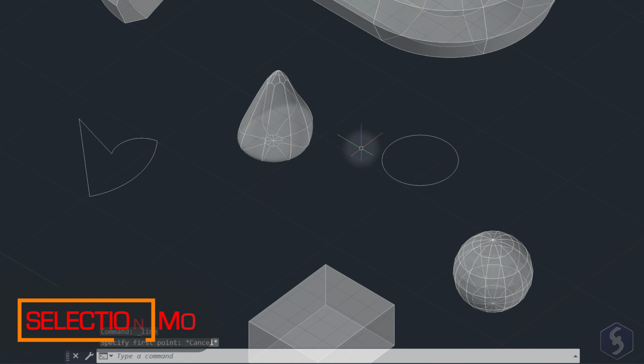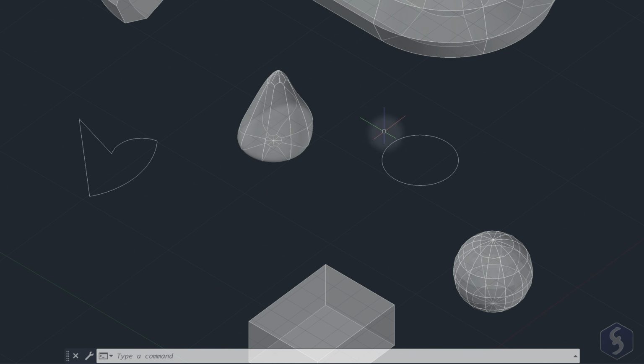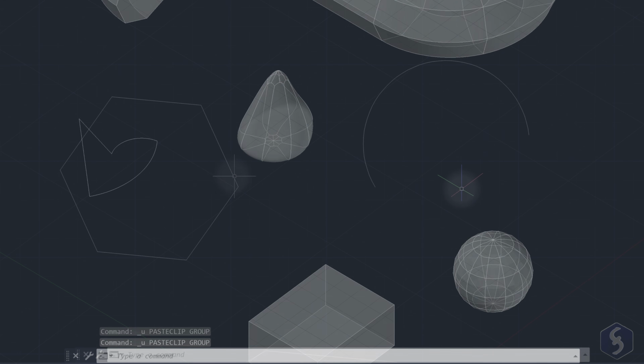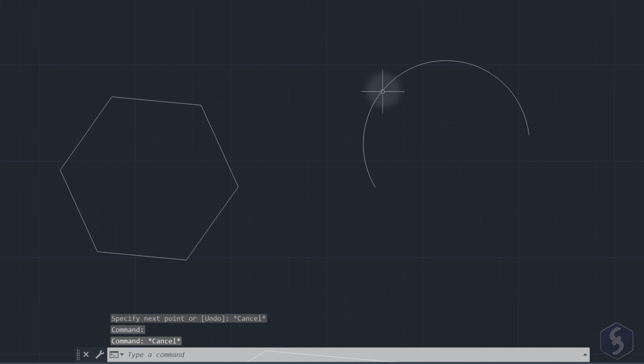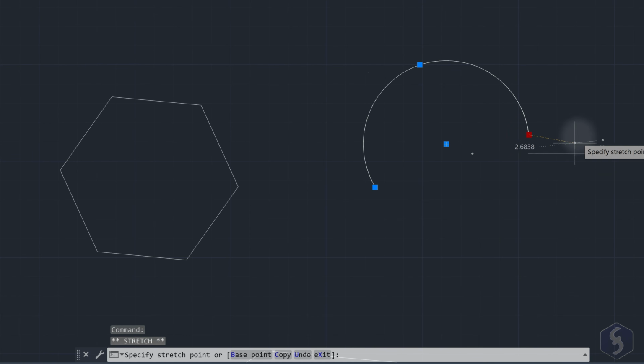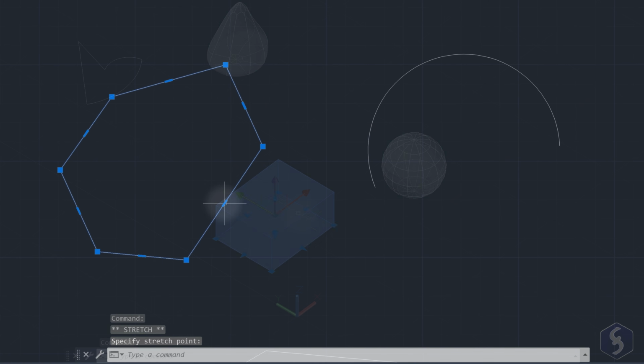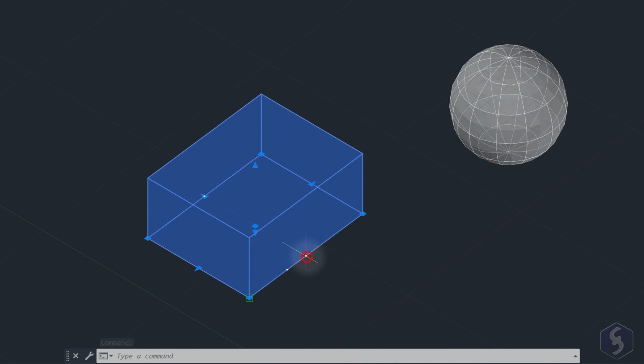When no tools are enabled, the cursor is in selection mode, showing a small square within it. In this case, click on any object to select it and use Ctrl or Command and X, C, and V to cut, copy, and paste it, and undo with Ctrl or Command and Z. Selected objects also display several nodes. Use the squares to move vertices or centers, the rectangles to move sides, and triangles to move faces or 3D extrusions.